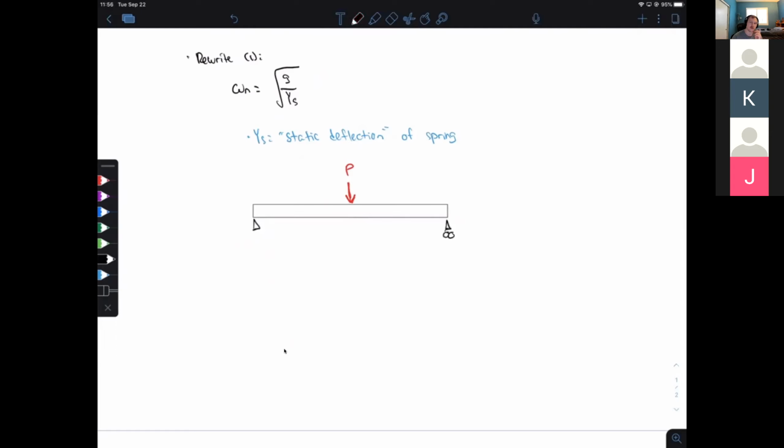Maybe I shouldn't have done it. I think both ends in the experiment are actually fixed, so whatever, it doesn't really matter. We're going to have some load in the center, and obviously this is going to deflect. So think back to 306A when you had your beam lab. You probably couldn't see the deflection because it was so small, but we measured that deflection with a gauge. And our maximum deflection was in the center where that load was applied.